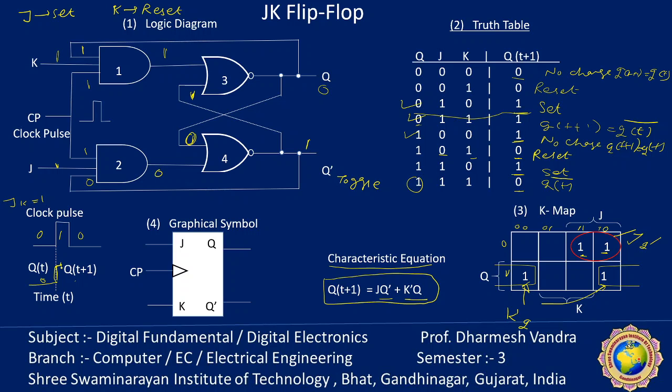Now remember that at that time, the propagation delay of the flip-flop comes into play. This is the propagation delay PD of gates 1 and 3, and the feedback reverses Q. So the flip-flop output changes again and becomes 0. After the clock pulse, the output is also 0.